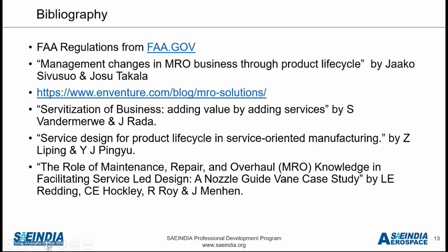A check is typically when an aircraft has flown, let's say, 200 or 300 flight hours or 300 cycles. That is a typical range, which means Airbus will provide a different range, Boeing may provide a different range, and for different types of aircraft, for A320 or 737, they will provide different ranges for doing the A check. For other aircraft, they will provide a different range.